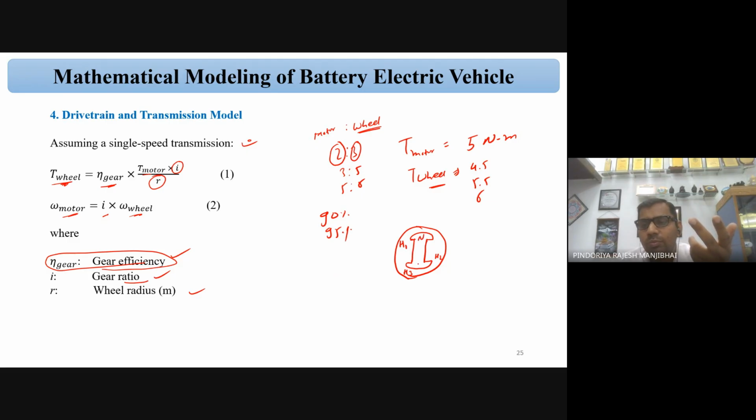Maybe this is the north pole and this is the south pole. Where is the north pole? It is near Hall effect sensor 1, and near Hall effect sensor 2. Based on this rotor position, we can rotate our rotor, correct? We have an electronic commutator, if you remember, with 6 switches, and based on these switches we can operate the BLDC motor.